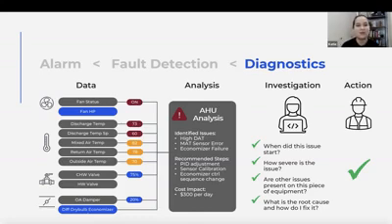So it takes all of this information. It says, I know I have these 3 problems. These are the recommended steps you should take. Either you need to adjust your PID, you got to adjust your sensors, or you have to do a change to your economizer control sequence. Those are the 3 top recommended steps. So right there, you have some actions to take right out of the gate. So it really saves a lot of desk time and time in the mechanical room, troubleshooting, and potentially going to get the part to come back, right?